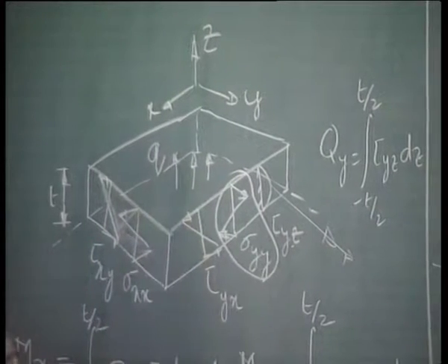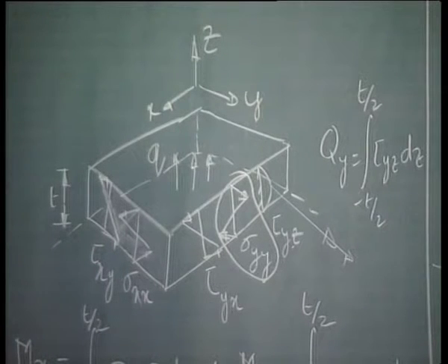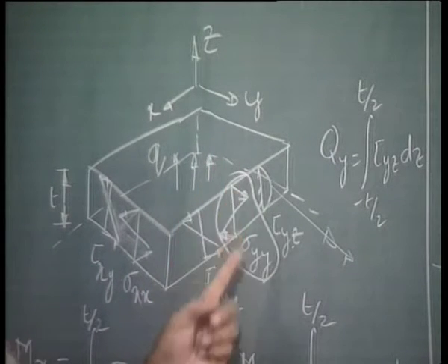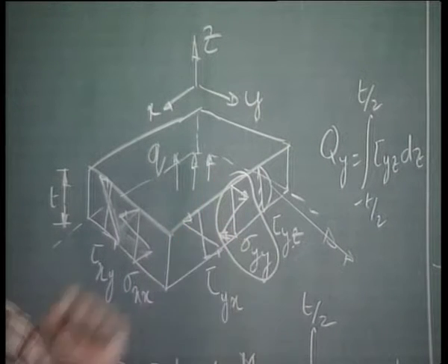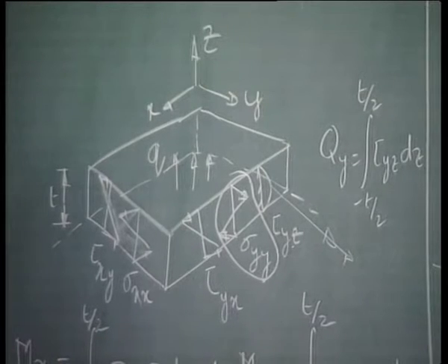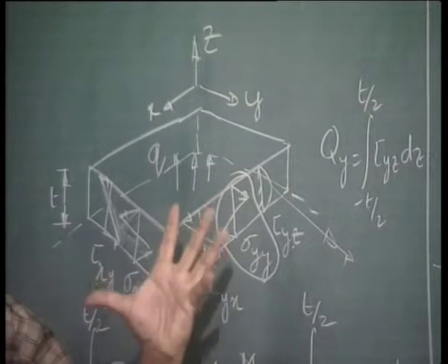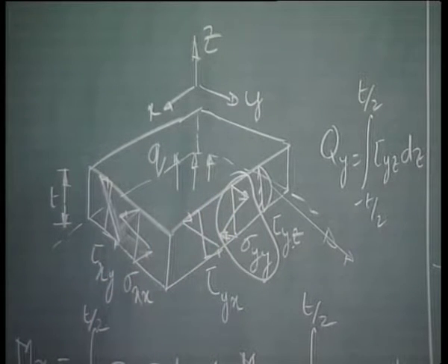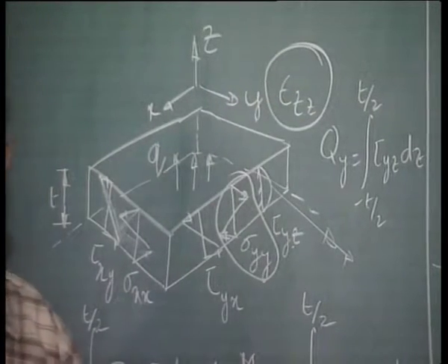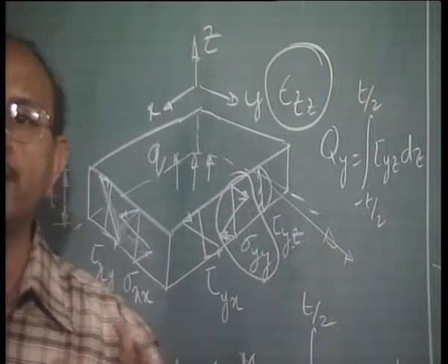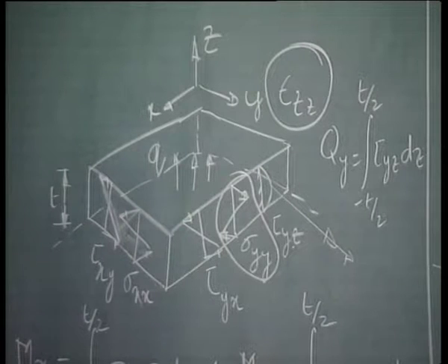When I replace this with our familiar 3D solid element, then z direction stresses, and hence epsilon zz, are going to be present. What would happen? The terms which indicate the stiffness of epsilon zz are going to be quite large when compared to other stiffness terms.